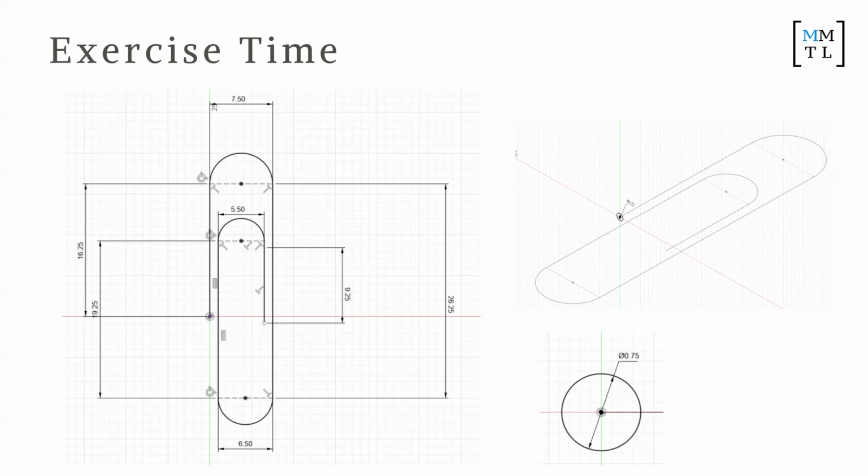Also, instead of using circles, you can just use the semicircle. There's an arc command in the sketch, like 3-point arcs and different arc tools. You can either arc, or circle and then put a line and trim the other half. Whichever is easier. Try the arc.